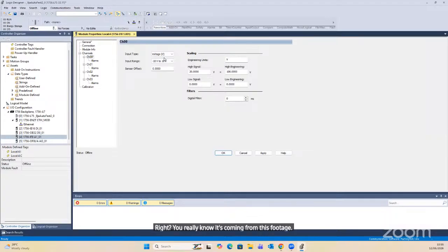The sweet thing about Studio 5000 is that, very much unlike Siemens, where you need to do your NORM_X, SCALE_X for scaling, you can do your direct scaling from your hardware configuration on Studio 5000. Yes, there's a scaling function inside Studio 5000 itself, but you can scale from your hardware configuration for Studio 5000.